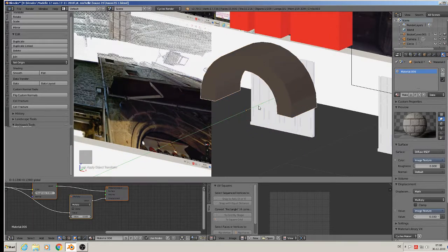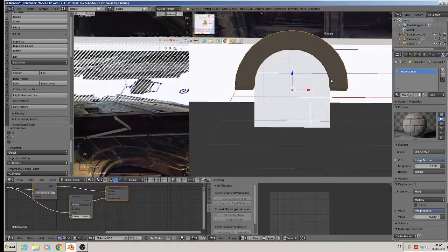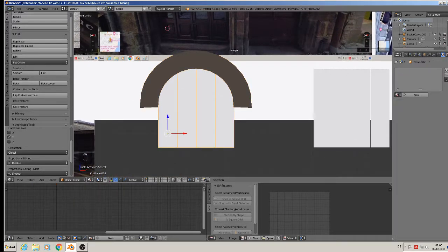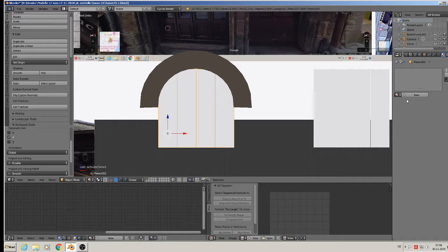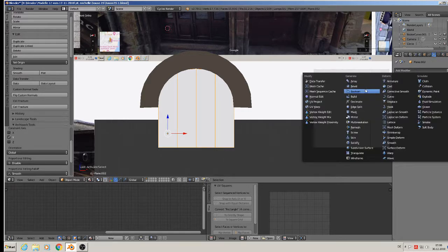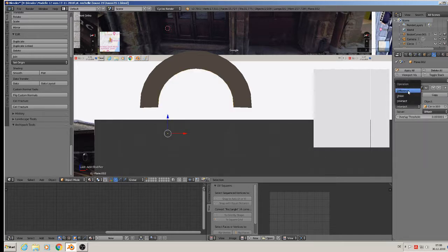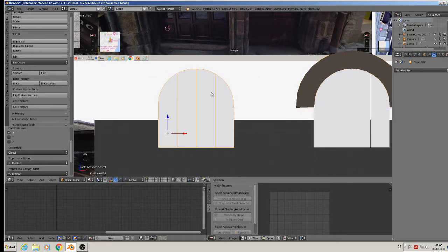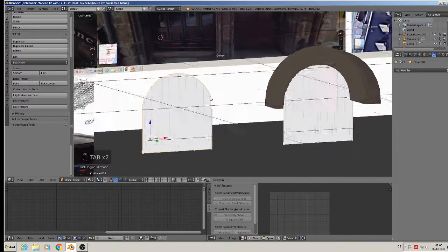Now we bring the cutting object over our door window stuff there. And now we take a boolean for that. So we go to the white one and the cutting object name is Circle 3. So cutting window object, modify, boolean, here it is Circle 3 and it should be the difference, apply. Well, we now get them away. You see it's a perfectly rounded cut here. And so we have what we need.